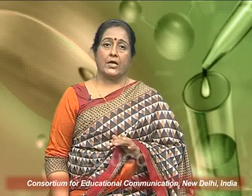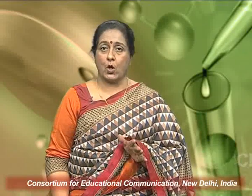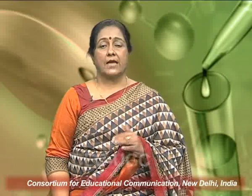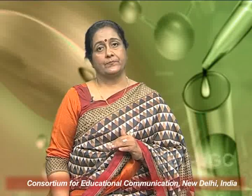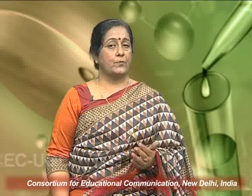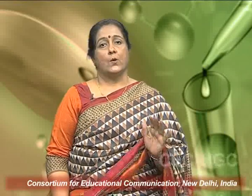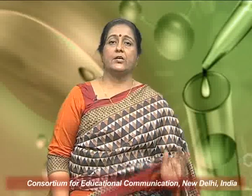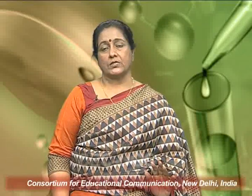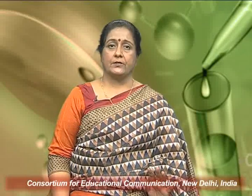Complete fluid lubrication is provided in delicate instruments such as watches, clocks, guns and light machines such as sewing machines, scientific instruments, etc. The most satisfactory and widely used lubricants for this type of lubrication are hydrocarbon oils, which are blended with selected long chain polymers in order to maintain suitable viscosity of the oil in summer, winter and other seasons of the year.